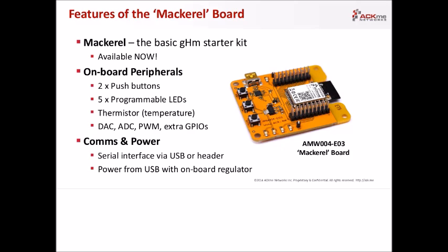It also has a serial interface via the USB, or if you prefer, you could plug a UART into one of the headers. That's 3.3 volt UART headers in this particular instance. You don't need external power or anything like that. The board is powered completely via a good USB cable, and away it goes. So that's the features of macro, which is the basic starter kit.